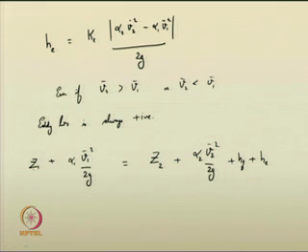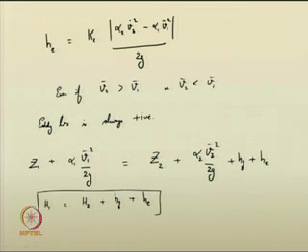So, you know what is Z1, what is Z2. Ultimately, what does this bring? This gives you the principle H1 is equal to H2 plus friction loss plus eddy loss. This is the fundamental principle which we have studied even in your undergraduate levels. So, this relationship is the governing principle which we are going to use for the standard step method.